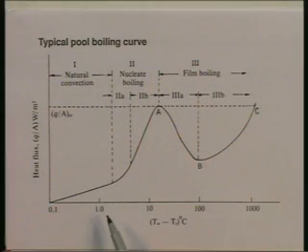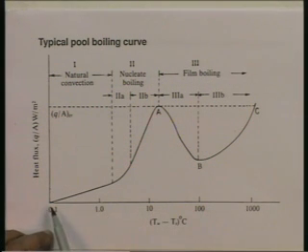Now, if you do this experiment for a pool of saturated liquid, a typical pool boiling curve which you will get is as follows. This is the pool boiling curve that you will get. On the x axis, you have T W minus T S and it is on a logarithmic scale. So, you can see 0.1, 1, 10, 100 and 1000. These are the values of T W minus T S which we are controlling during the experiment.